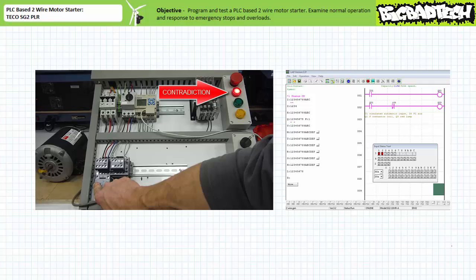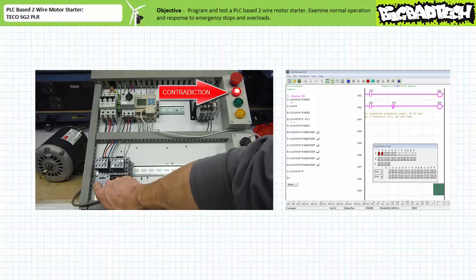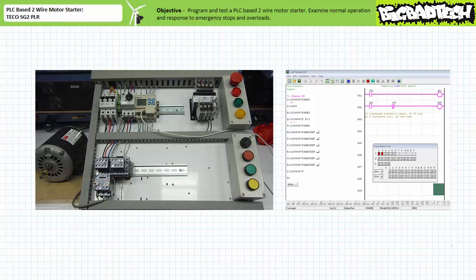A potentially deadly situation is coiled and waiting to strike when the overload cools and is manually or automatically reset. Luckily, the logic in rung 2 indicates a contradiction has occurred in that output Q1 is asserted, however the F1 auxiliary contact is not closed. The red lamp is on, indicating that something is amiss. An operator or a technician can take the necessary precautions and lock out and tag out the system to investigate the source of the overload.